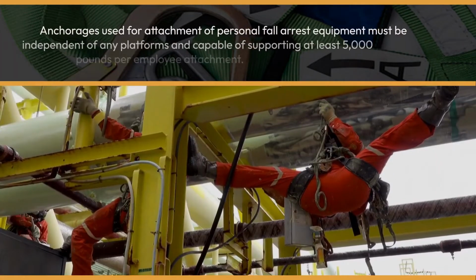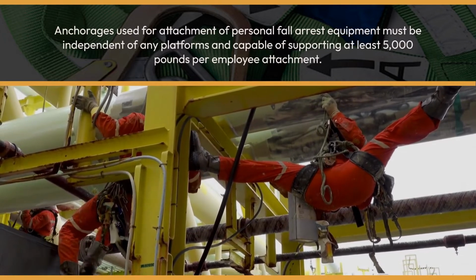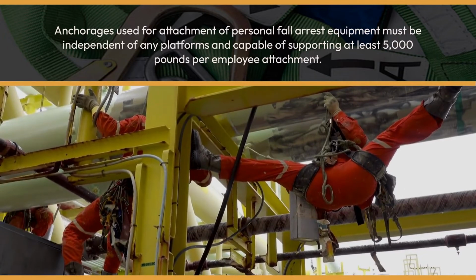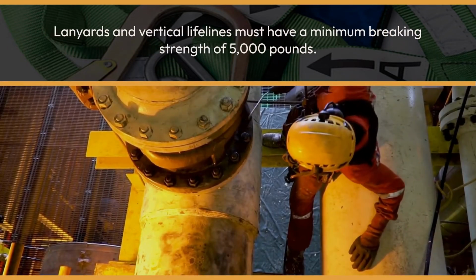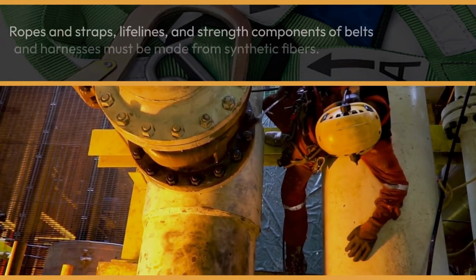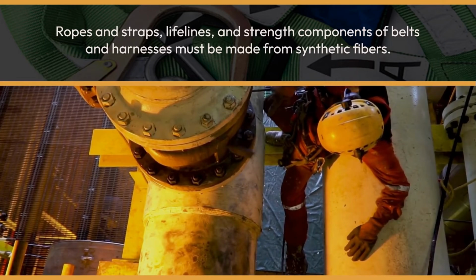Anchorages used for attachment of personal fall arrest equipment must be independent of any platforms and capable of supporting at least 5,000 pounds per employee attachment. Lanyards and vertical lifelines must have a minimum breaking strength of 5,000 pounds. Ropes and straps, lifelines, and strength components of belts and harnesses must be made from synthetic fibers.